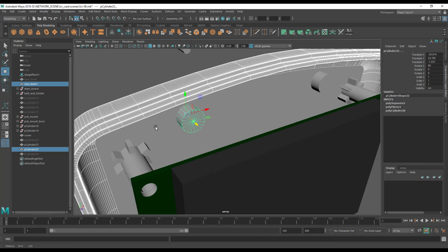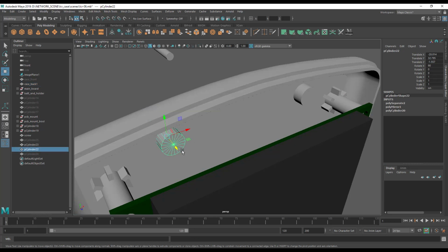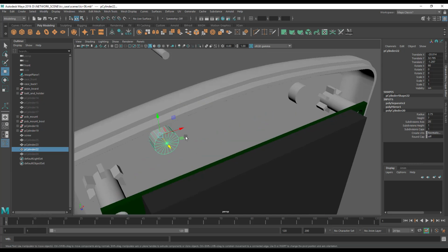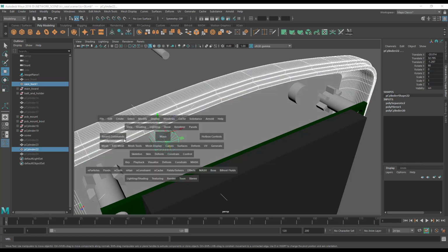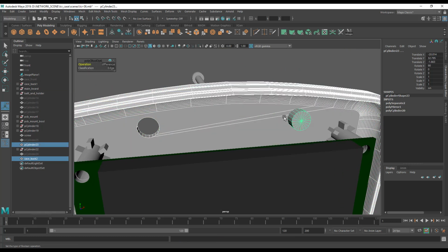In fact, what I'm going to do is, whoops, let's not select both of those. So these cylinders are 7mm. That was right, wasn't it? So let's duplicate these and make, actually let's just make the holes in the back first. We do have a spare set of these cylinders, I believe. So yeah, let's just make the holes first. So Mesh, Boolean, Difference, that should punch a hole through the back here. And the same thing again, just hit G and you'll repeat the last command, of course.